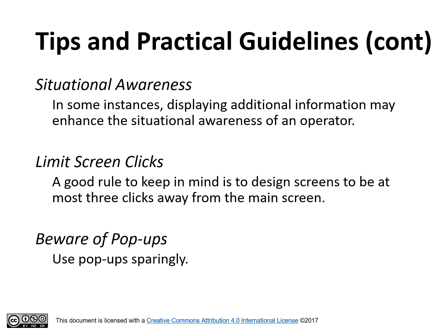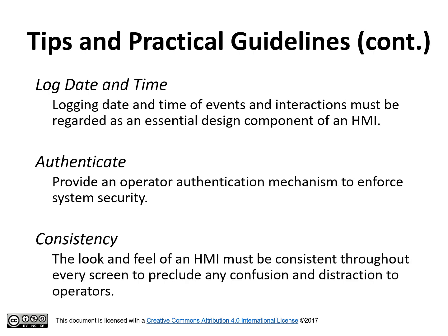Beware of pop-ups. Use pop-ups sparingly. Excessive use of these displays adds very limited advantage and can be a distraction to operators. Log date and time.